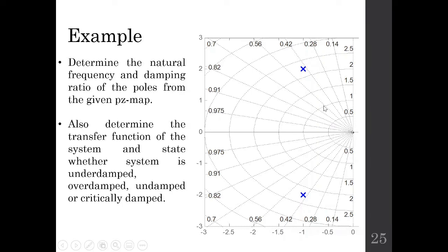Okay, I'll quickly explain this graph. Now here is your pole value. In order to find the value of omega n and zeta, you simply need to find where this pole is connecting to this line and to this line. Here it is cross-sectioning somewhere here.